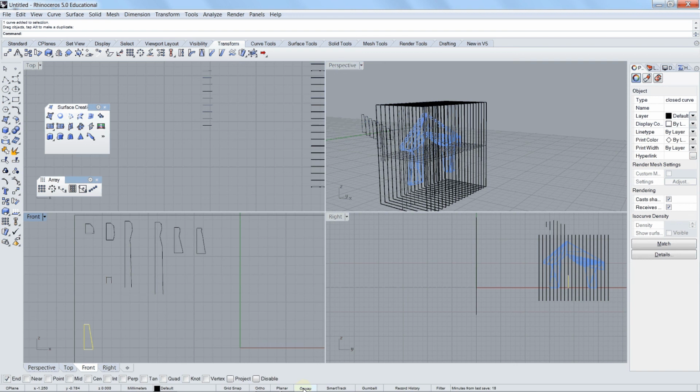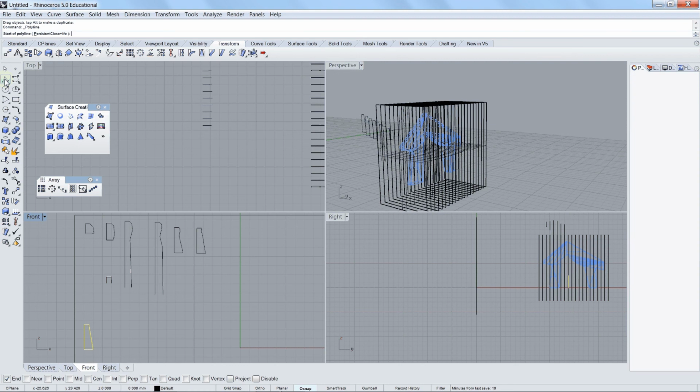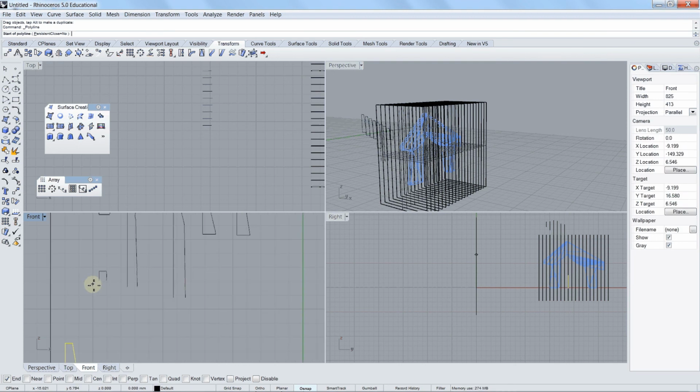So what I'm going to do is put my mouse down to the bottom, and we have an OSnap selection button here. I'm going to click that, which turns these things on. And I'm going to make sure that this box is ticked to the endpoint object snap. What that will let me do is select our polyline, and if I go down here, it will automatically snap to the end point of that line and connect to the end point of that one.